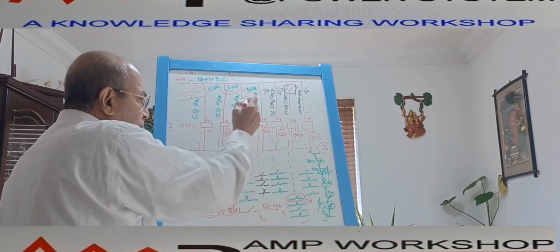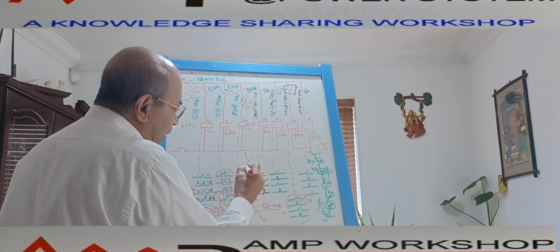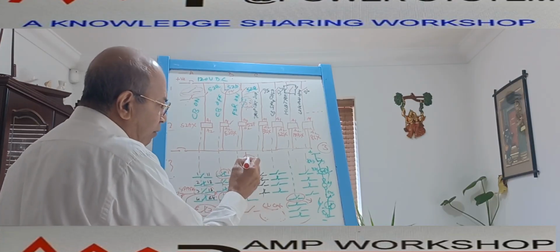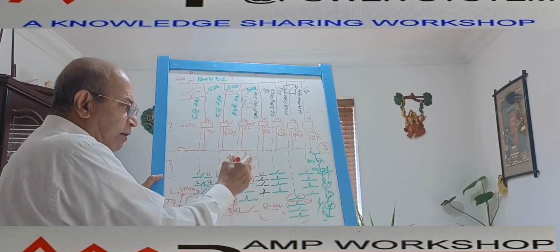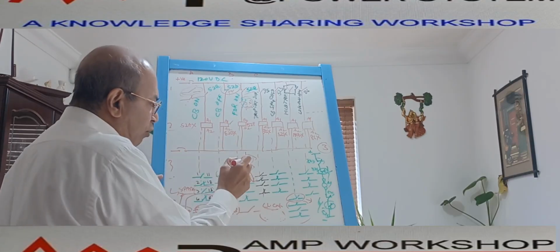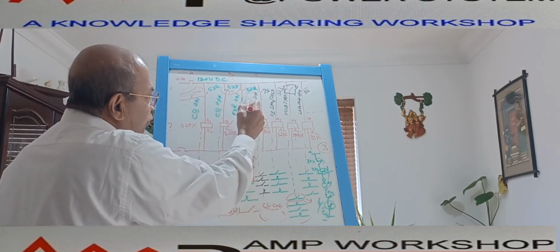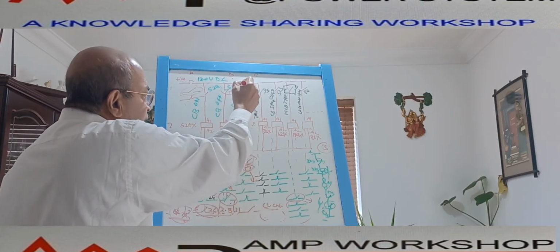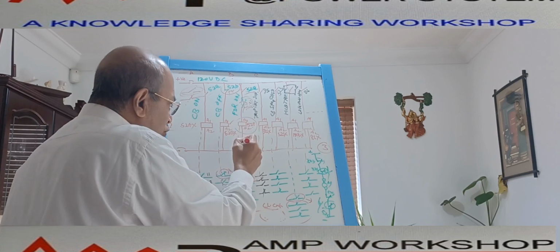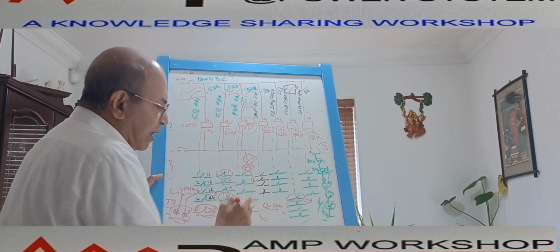We have seen that this is the isolator and this is a circuit breaker, and the power is going like this. So if this is on and the circuit breaker is on, then only power will flow. At that condition we say this feeder is on. That is our terminology. To get that, I need the isolator on and the breaker on. These two conditions are given to an auxiliary relay 52F, and the 52F relay auxiliary contact we can use for the feeder on indication.